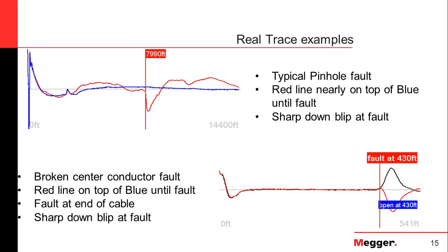You know, this is a pretty broad topic, but in general, the TDR cannot tell you what level of concentric neutral damage you have. You can get an indication from how bumpy the trace is that there's some concentric damage and microimpedance changes up and down the cable.